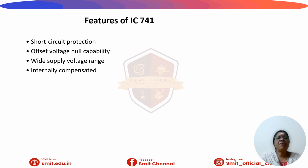The key features of IC741 are high voltage gain, which offers very high open loop voltage gain, typically in the order of 200 volt per millivolt, that is 100 dB at low frequencies. High input impedance in the order of 2 megaohms, so it draws very little current from the input source. Low output impedance in the order of around 75 ohms, enabling it to drive various loads efficiently.